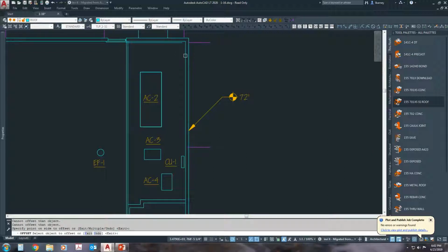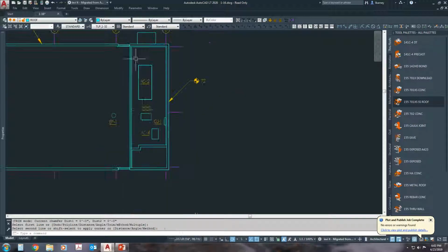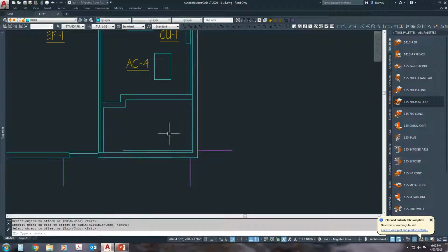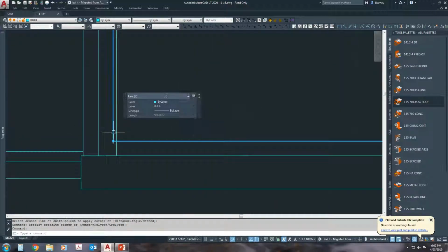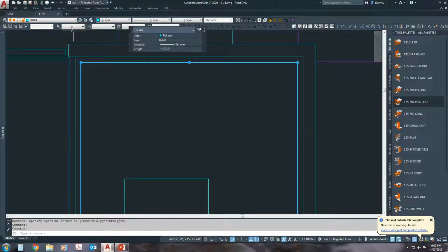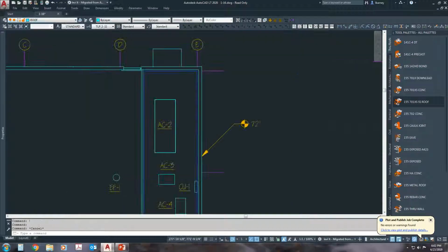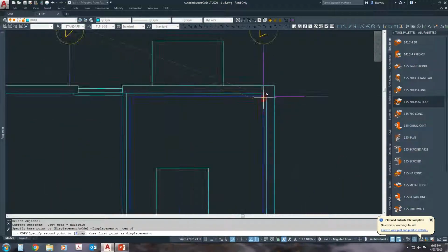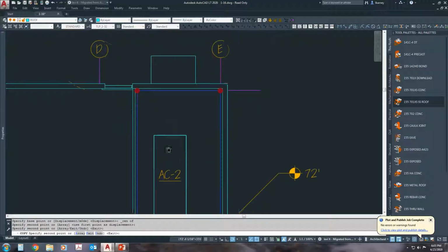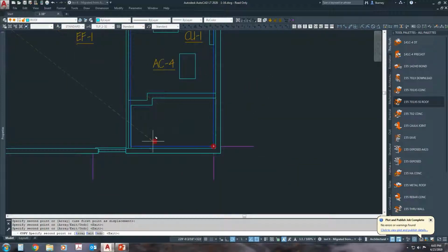What I start to do is offset the parapet wall approximately 6 inches. And what this does is give me a nice offset so I can change it to the cable layer, which will interconnect all the air terminals. I'm going to select the air terminal symbol from the legend and start by placing them at each corner.